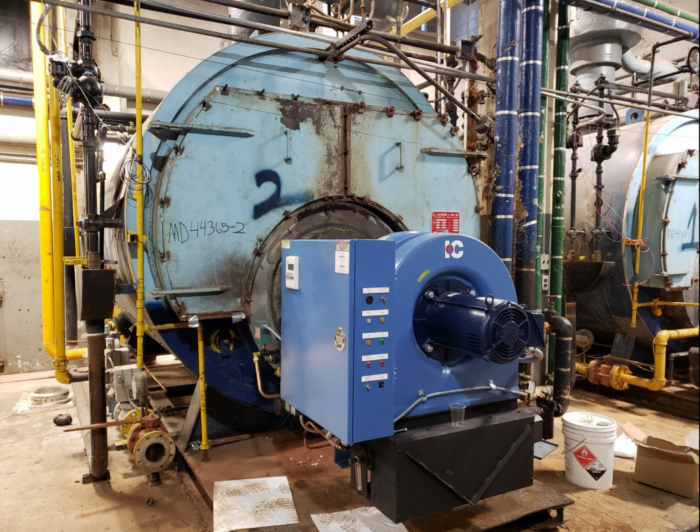So now, let's just say you got your cutout at 2 psi on this boiler, right? Your burner shuts off. Your burner has maybe a 30-second post-purge of just blowing cold air inside of the combustion chamber and inside of your tubes. Let's say the relay is 2 minutes, even a minute long is still a long period of time. Your vapor stat kicks in and calls for heat again.